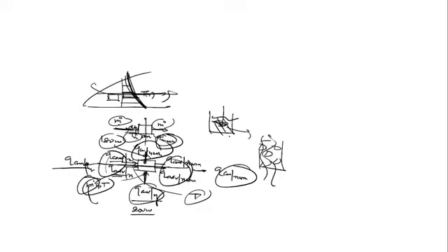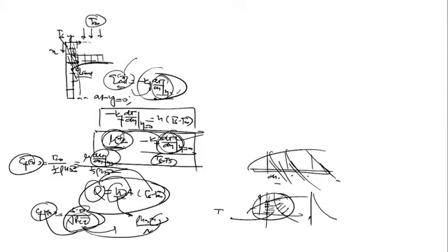In those complex cases, you are not supposed to find the temperature distribution, because once you find the temperature distribution, you can find the rate of heat transfer by convection by knowing dT/dy at y equal to 0, the gradient at the wall. Even if the flow is very complex, at the wall the fluid is always stagnant and heat transfer initiates by conduction only.